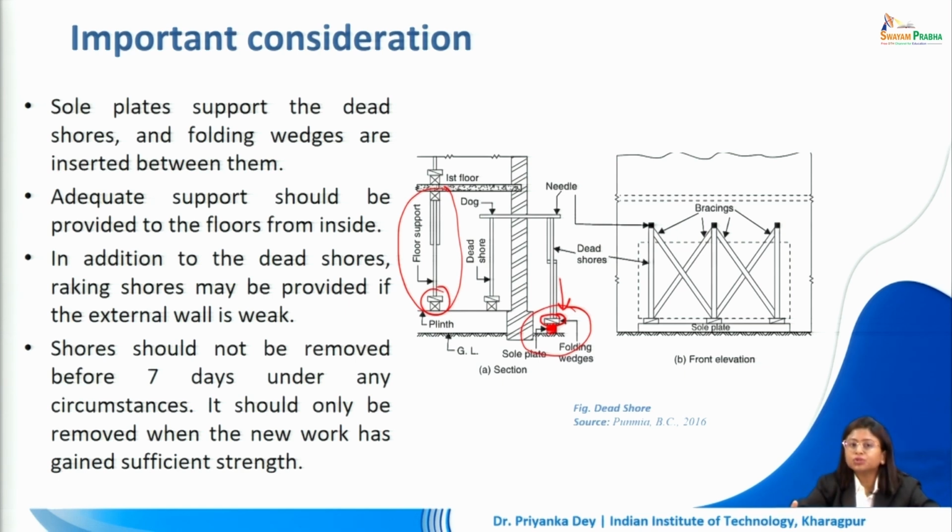Now, shores should not be immediately removed after the construction has been done. We need to keep them for at least 7 more days. They should be removed only when the new work that we have done has gained sufficient strength and we know that the structure is now stable.